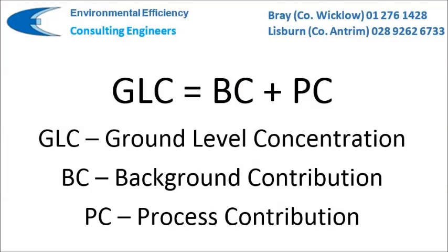The actual concentration of a pollutant at ground level, termed the ground level concentration, will be made up of the background level, often called a background contribution, and that due to the stack, termed a process contribution. The background level can be found from data recorded by the EPA air monitoring stations, and there are a number of these around Ireland. The process contribution is calculated by the air dispersion model.